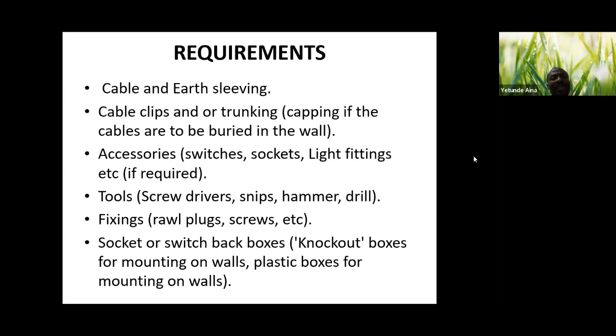Now, to carry out any electrical installation, there are some requirements that are fundamental. These requirements are sacrosanct, and we need to ensure that all these requirements are in place before any installation can be done. To start with, we have the cable and the earth sleeving. We have the cable clips. Cable clips come into play when we are talking about the surface wiring and the trunking. Then we have the conduits, capping if the cables are to be buried in the wall.